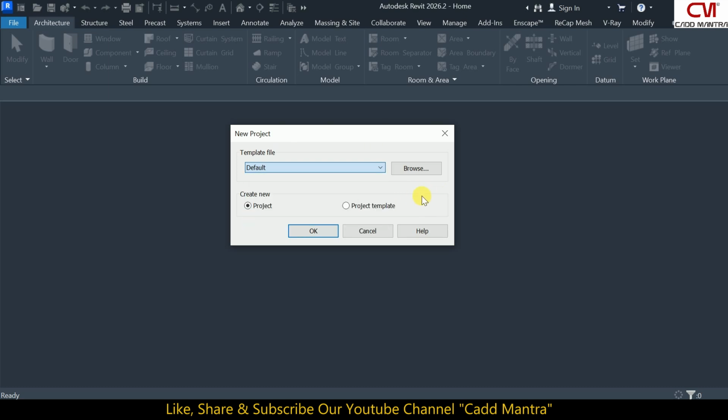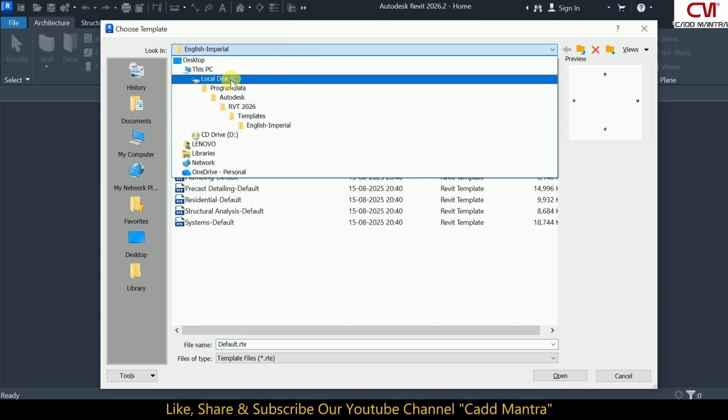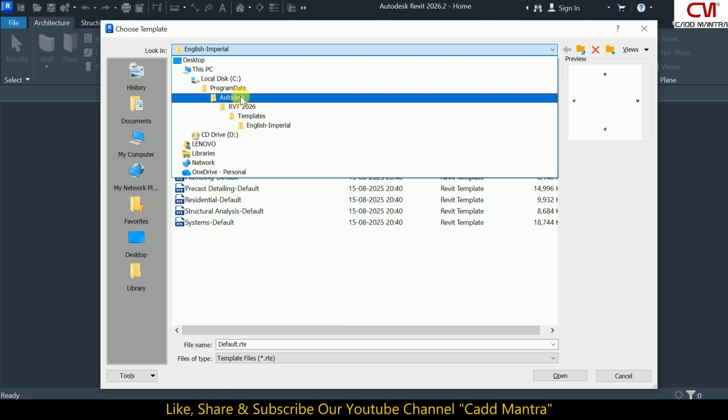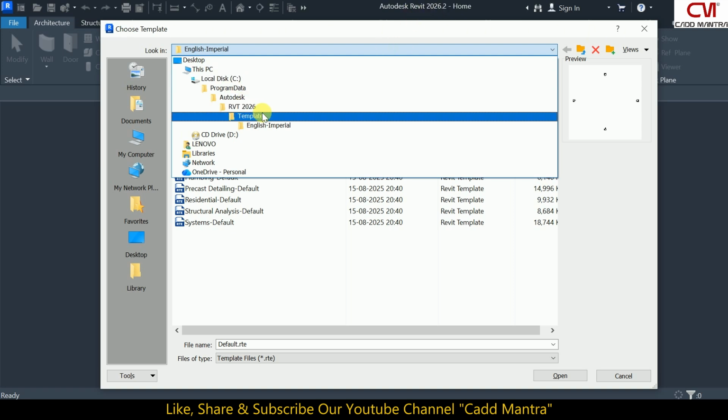You go to browse. You might not find this file in this location in particular, so we will want to go to browse, and particularly in this location, that is C drive, then ProgramData, then Autodesk, and then Revit 2026, that is the version that we have installed in our system.